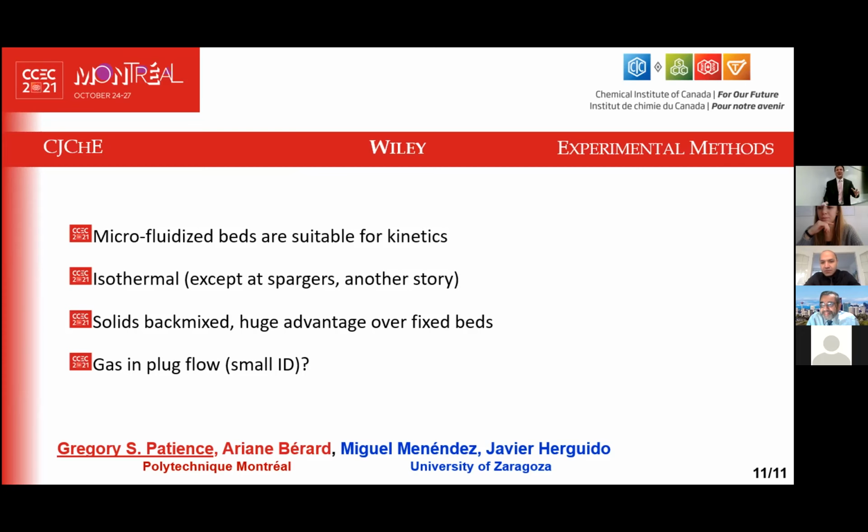That's a huge debate, okay? And everybody says I'm wrong. I use the catalyst that I want to use commercially. But Glicksman at MIT and the folks in Austria will actually change the particle characteristics. When I say microfluidized bed, I am looking at about 10 millimeters. And what I'm interested in is the kinetics. If I'm doing hydrodynamics, then I might have to do the scaling. I still don't want to do it, but people suggest that you have to. But not for the kinetics. For the kinetics, you've got to use the catalyst that you want.